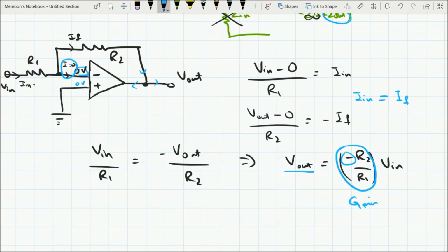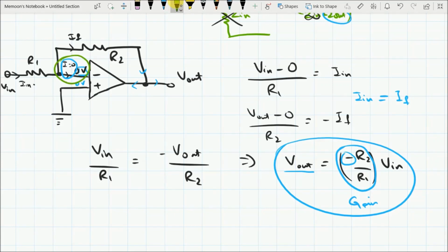And now we can actually calculate that if our V out is equal to this value, this will mean that a 0 is here at the negative input terminal to make it equal to the positive input terminal. If you put this in equation number 2, you will find out that there must be a 0 at the negative input terminal.